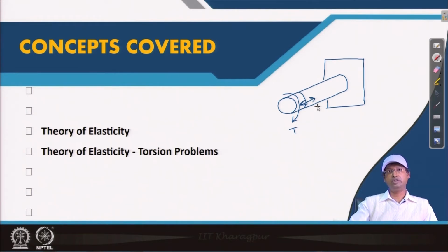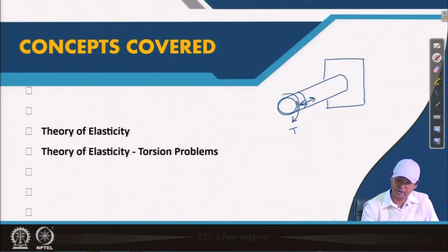That is what we said as out of plane displacement. So, out of plane from the plane of the cross section of the circular member. So, if there is some displacement out of plane, we call that warping. Warping is a phenomenon we need to learn, because practically, if it is a non-circular section, we observe warping in a very predominant way.